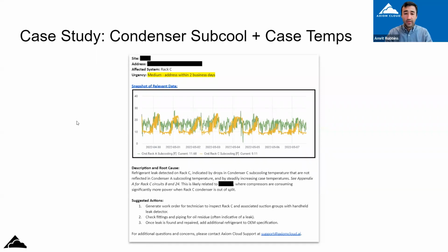And again, the cool thing here is that this is where the digital twin model is able to detect a refrigerant leak without a receiver level sensor at all. And this one was also confirmed. There was a leak confirmed by a technician. It was repaired, it was refilled, and that catastrophe was avoided. So yeah, thanks, Turner.